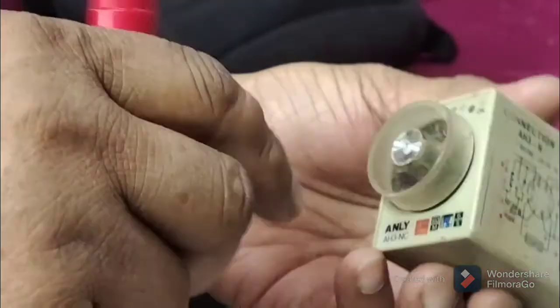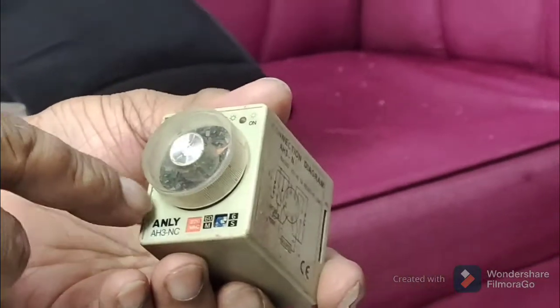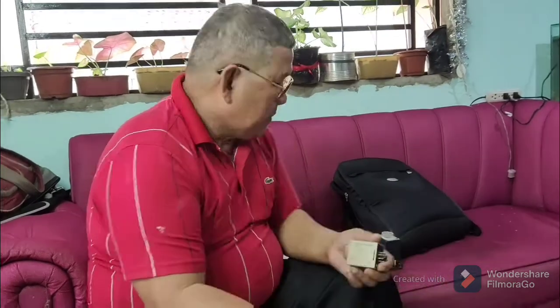So this is an AC/DC timer. Okay, this is an AC/DC timer, and this timer is good for 250 volts, and good for 5 amperes. So if you think that the device is more than 5 amperes, do not use this. When you say 5 amperes, that is the ampacity or the contact rating of your instant contact inside.